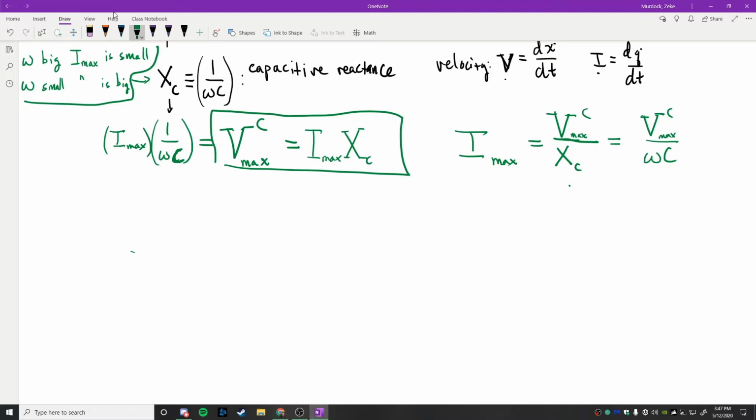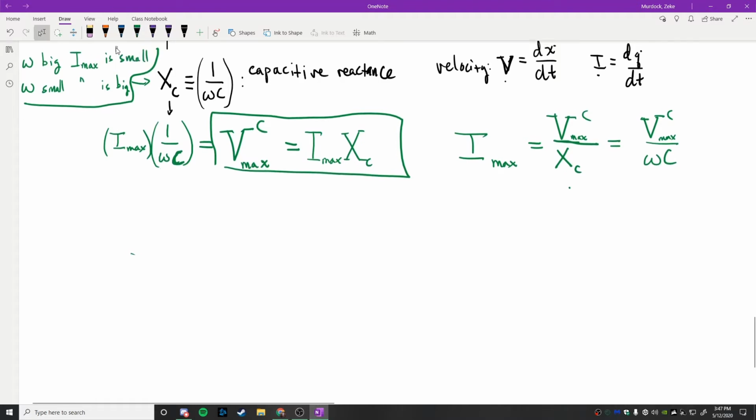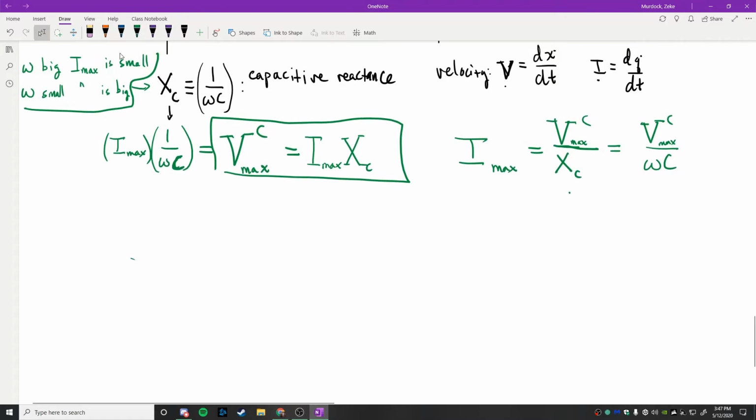Oh, wait. I got it backwards. I was about to say something that sounded not true to me. Yeah, it's kind of weird. I also wrote it over here wrong. My bad. Let me slow down for just a second and fix this. X sub c is 1 over omega c, right? So when I put this in here, it's Vmax divided by 1 over omega c.